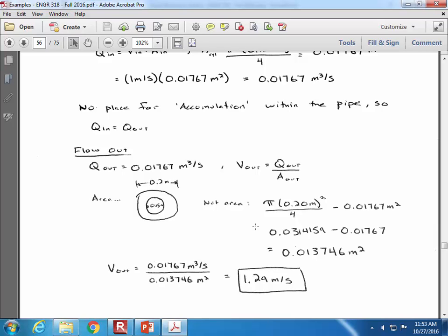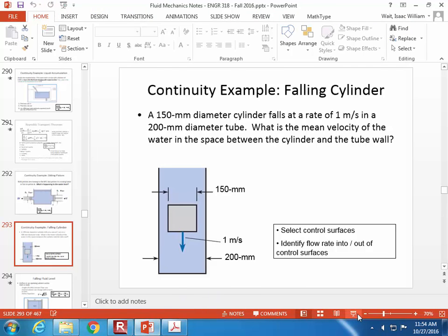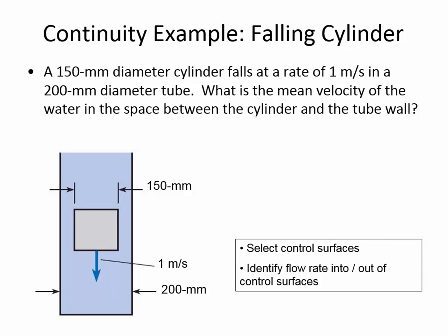So what's the tricky spots of this problem? When you're just starting with the picture from the example description, the tricky parts are maybe visualizing this in 3 dimensions, knowing where to put the control volume. You know, I drew it on the whiteboard there, but you have to think about where you put the control volume. It should encompass where something is happening. It should reflect where the water is being pushed by this incoming cylinder and where the water is exiting around the edges. And so if we drew our control volume to enclose the entire system, so let me raise the whiteboard, the projector screen, and show you what a really useless control volume would look like.